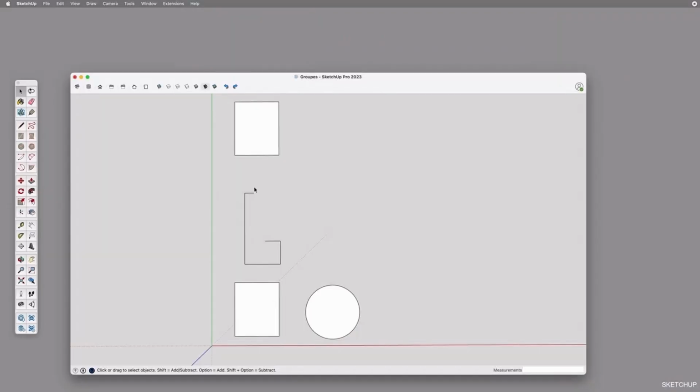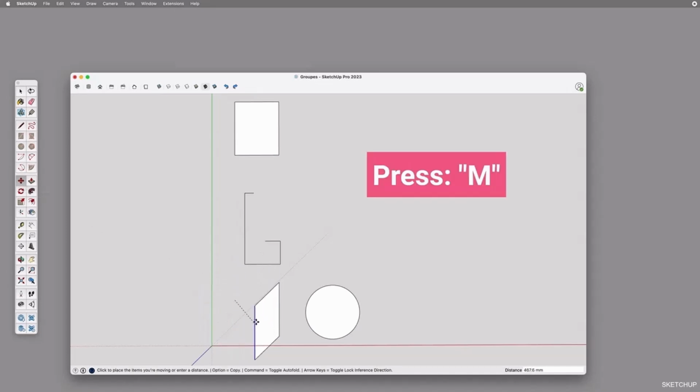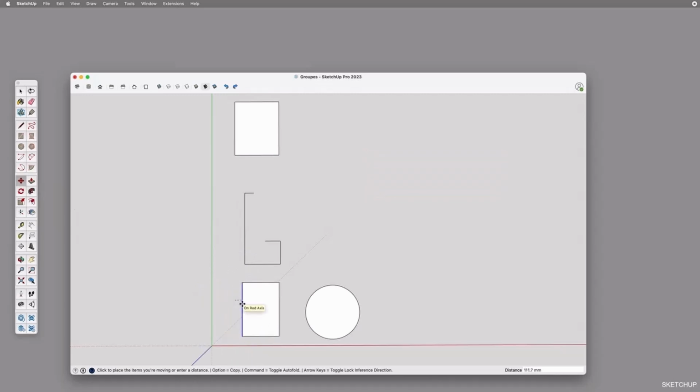In this lesson, we will talk about how to move shapes, meaning lines and surfaces, and how to copy, group, rotate, and scale them. For this lesson, I have created some basic shapes for you. Now, when I select my Move tool from my toolbar, or click M on my keyboard, and start moving a line, for instance, you will notice that the line is sticky to the whole rest of the shape. If I click on the surface, I can then move it. It helps to use your arrow keys to fixate an axis direction.